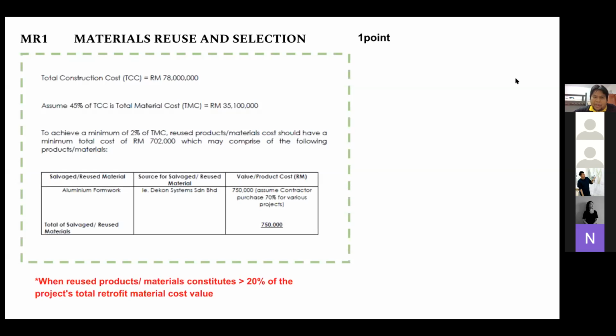There is a minimum amount of formwork on site because as far as I know, only a small part of the building would require formwork on site. The normal plywood formwork, because they're going to reinforce concrete in situ. But most of the stuff is already casted at the factory. So to get verification, you better call up Architect Suria or the contractor.